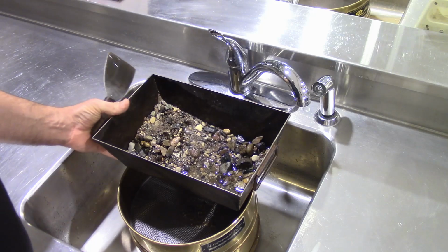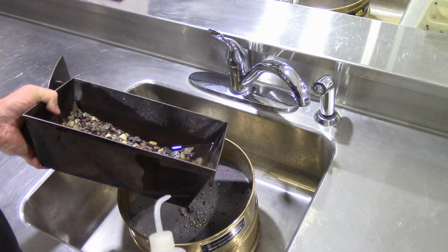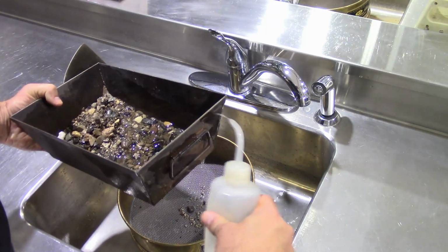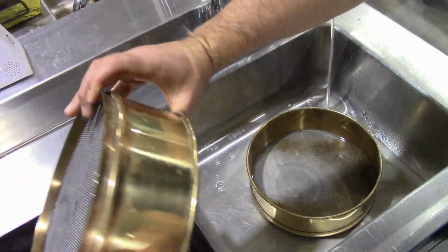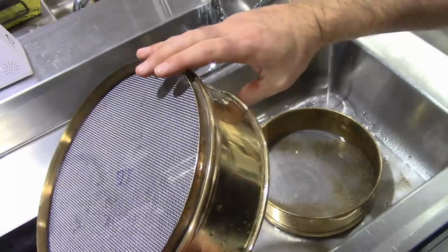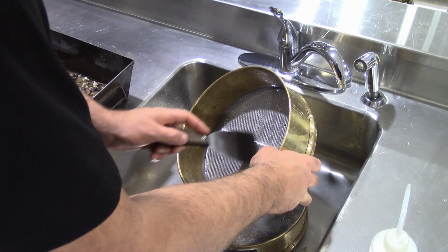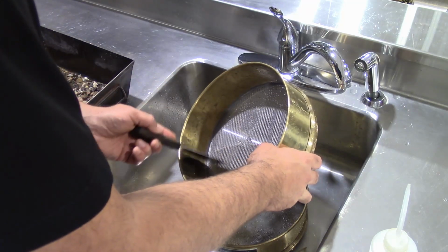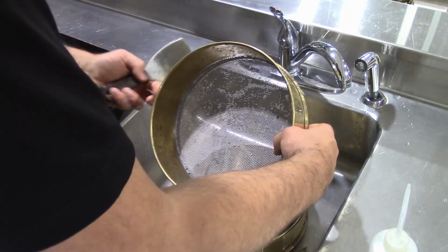Next, use your tool or water to gather all the material contained on the screens back into your sample pan. We want to ensure that all material retained on the number 16 and number 200 screens is reincorporated back into the sample pan. Since the loss by wash test measures how much material is lost past the number 200 screen, we don't want to inflate that value by leaving any retained material behind on the screens.